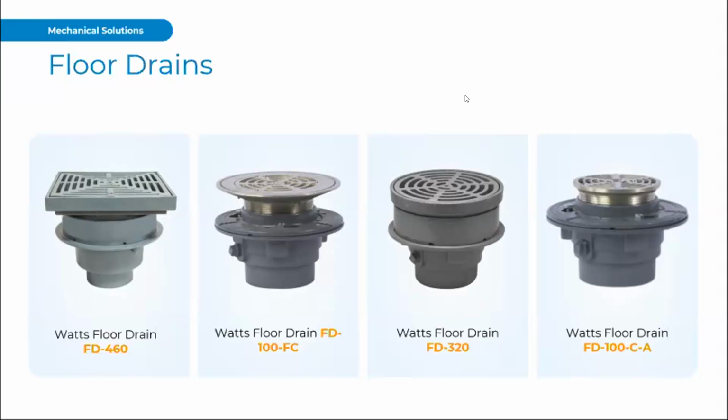The floor drain body has an epoxy coating that lasts longer, has great protection for the drain. You're not going to get a couple years down the road and have rusting and pitting. You can see the trap primer connection, standard feature. One thing I would note is, take note of where the membranes are in your flooring. If you only have the surface membrane, then you may be looking for an FD200, where you just have the 200 FC with the surface membrane clamp and a poured bed that it sits in.